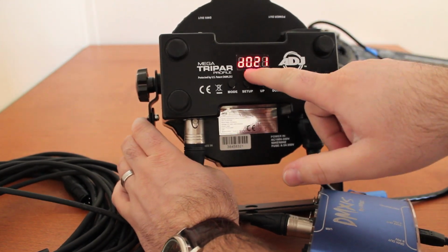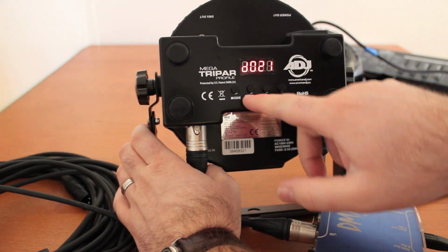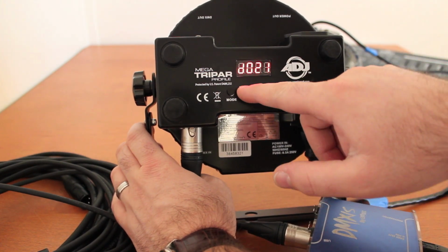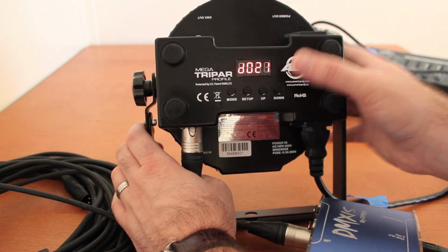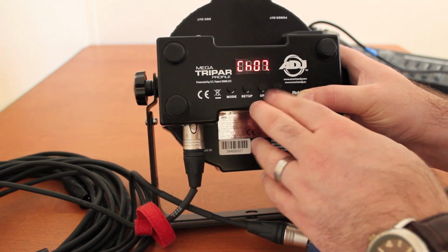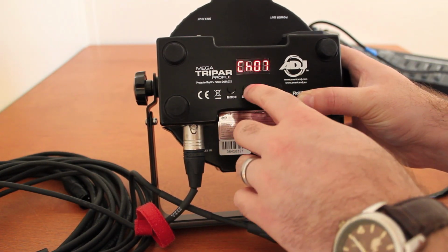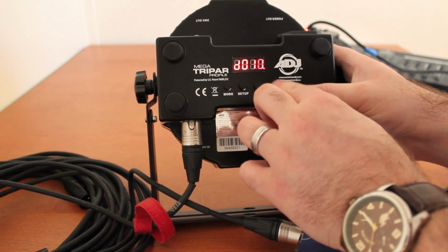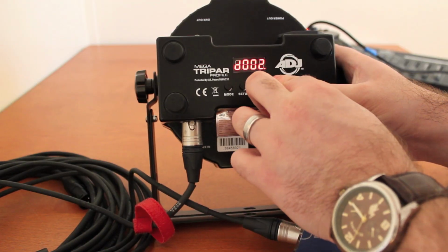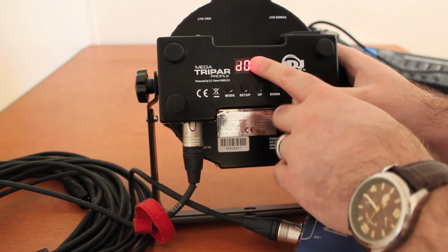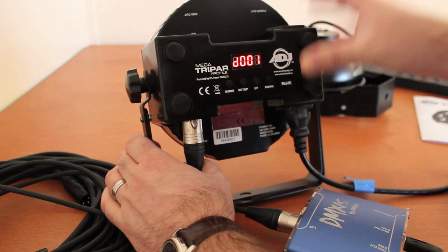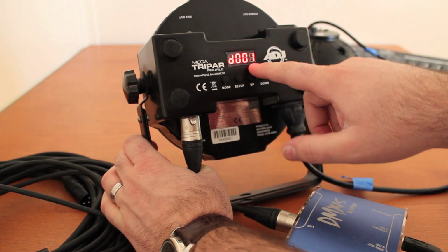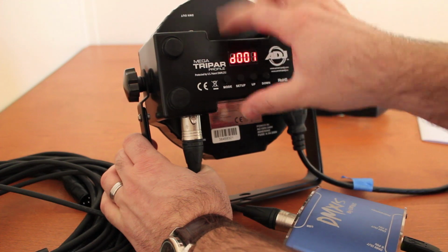As you can see, the light stopped blinking here. The mode is already on DMX. The channel is 21, but as we saw earlier, we're going to make this channels 1 through 7. So we're going to make sure that it's on 7-channel mode. We're going to go back and bring this down to channel 1, because that's the starting channel this light is going to start on. So this is on channel 1. You'll see when we go back to our software that starting on channel 1, those sliders will control this light.